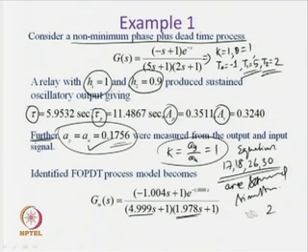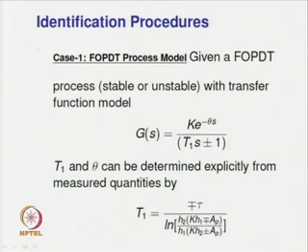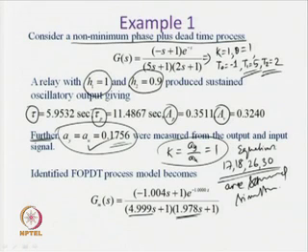So, using the identification technique, it is possible to estimate the parameters of a transfer function model accurately. This shows the efficacy of the powerful equations we have derived earlier, based on the zero crossings and peak amplitudes of the output signal. Now, identification procedures for simple transfer function models: here you need to solve a set of analytical expressions. Keep in mind, you have to solve 4 highly nonlinear analytical expressions simultaneously using some routine, and often the solutions may lead to false solutions.